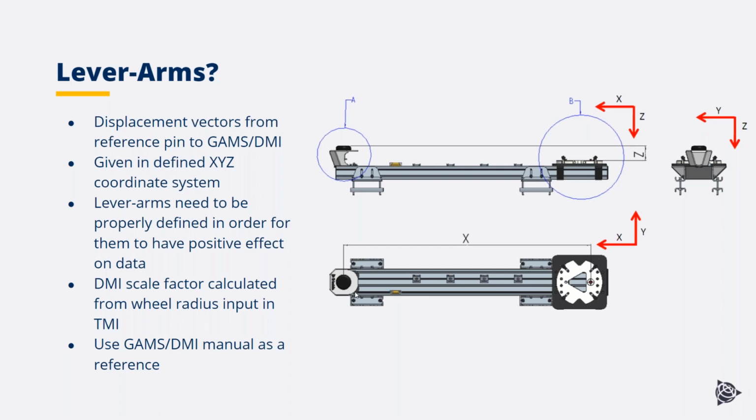I think it's something around 1.5 meters. The Y lever arm is probably close to 0, and the Z lever arm would be minus roughly 5 centimeters, a couple of inches. So that's an example of the axis and the directions of the values.